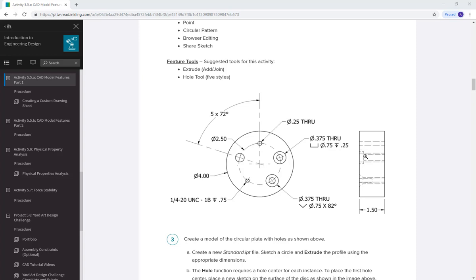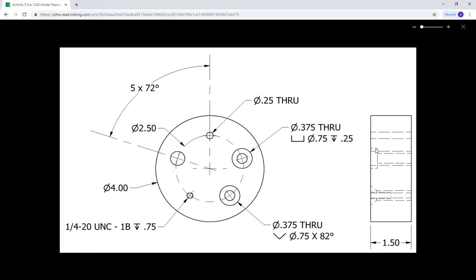So if we look right here, I'm going to zoom in a second, guys. Right here, this is showing the countersunk hole. This area right here is larger, and then this area right here is going to be narrower. So if we have a bolt, and you guys have all seen a bolt, which has a large head on the end, it can sit below the surface of our material, but it needs to have a larger opening. So this one is making that. And then this little arrow here means how far down this larger depth goes. When we actually make the holes, it'll be a little bit easier for you to understand.